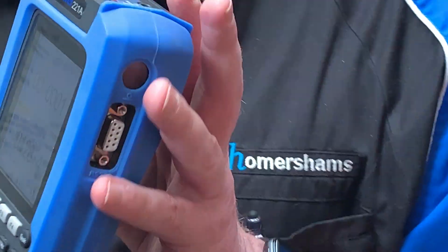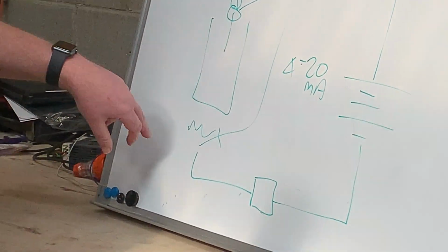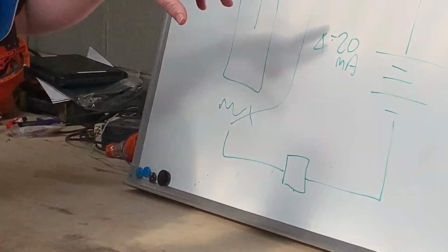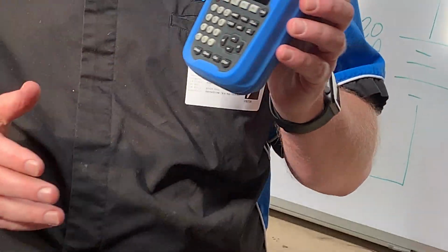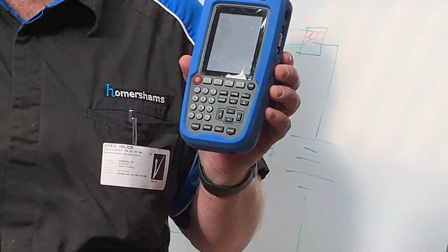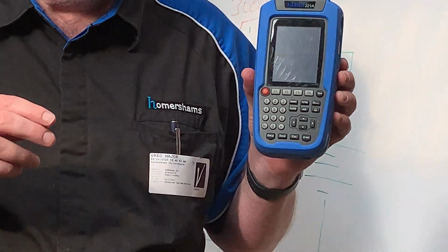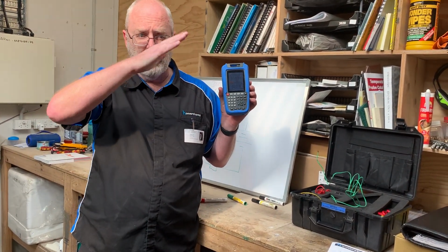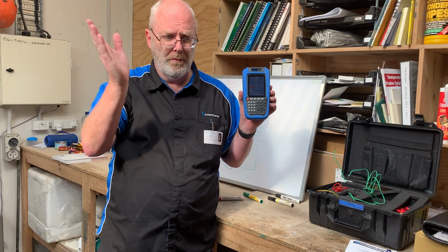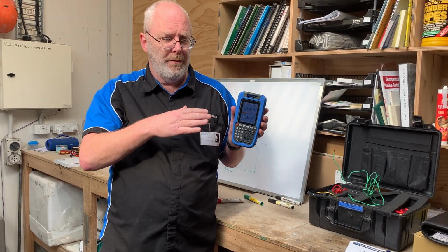And what you'd see here would be the flame going up and down. Just bear in mind, if you're doing this, you're on a live system, so you have to use some caution because you don't want to be cooking whenever you're doing this. But you can see that's marvelous, and as you raise it with the valve, you'd watch your valve opening and closing. And you could do the same with the other functions.